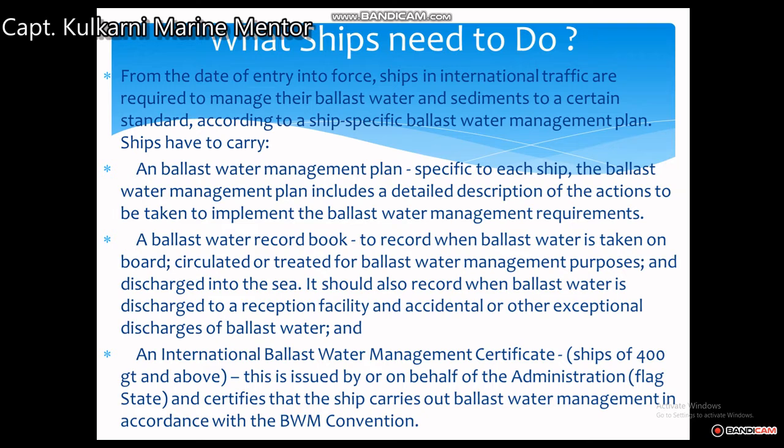An international ballast water management certificate becomes a statutory certificate. For ships of 400 gross tonnage and above, this is issued on behalf of the administration, the flag state. Either somebody who has been appointed by the administration, such as a classification society, can issue it, or the flag state will issue it, and it certifies that the ship carries out ballast water management in accordance with the BWM Convention.